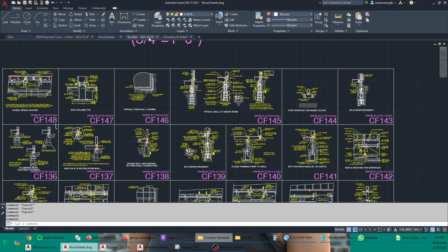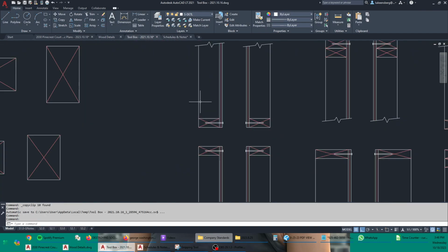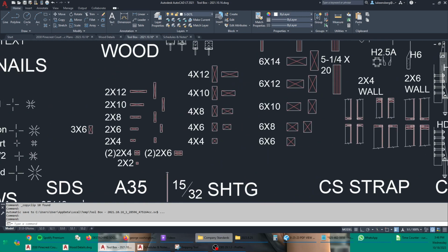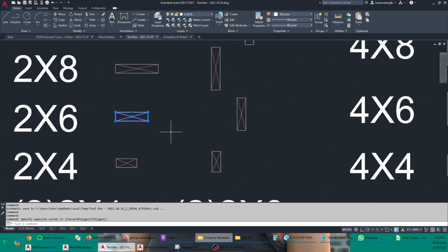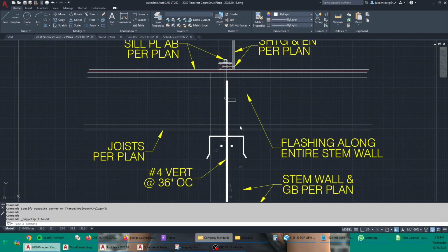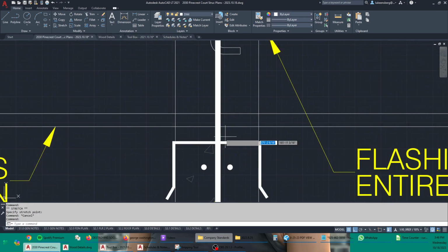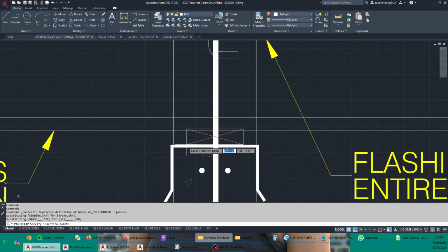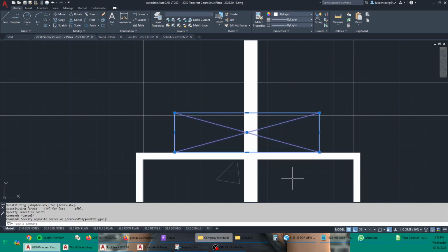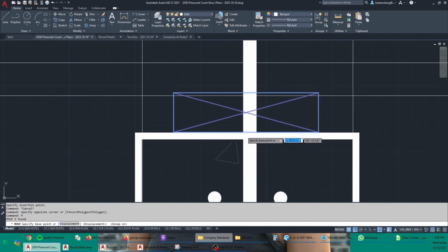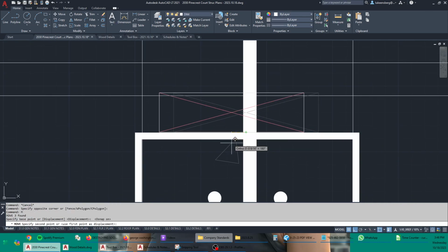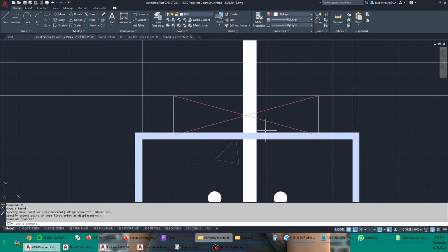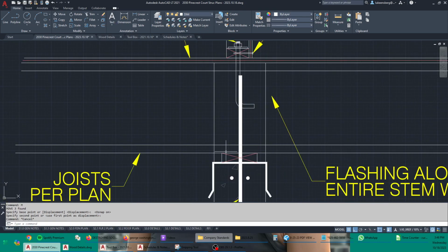Right, let's go to the toolbox here. Right, and there's a 2x6. Copy it, bring it over here, paste it, and we can just set it down right there. And I want it to be centered. I really try to be careful to draw things centered, so I'm using the OSNAP function to center that sill plate. This goes away. Whoops.